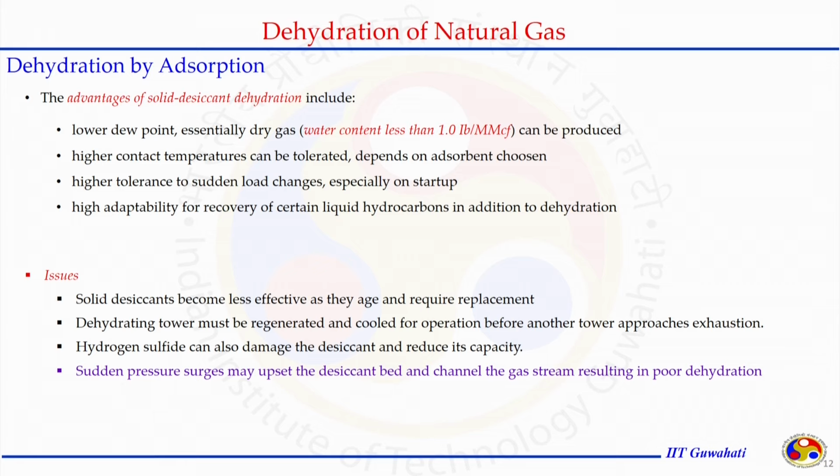Another advantage is high adaptability for recovery of certain liquid hydrocarbons in addition to the dehydration process. So, this packing, for example the granular silica gel packing, has adaptability for other contamination. Those could be some higher hydrocarbons present or some solid particles in the natural gas. Those can also be separated out in the dehydration process.